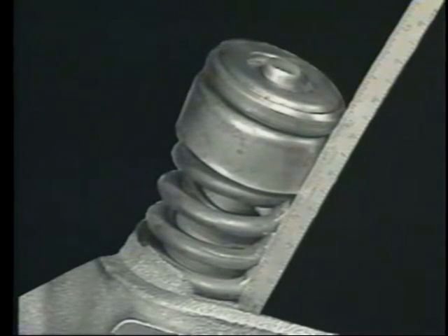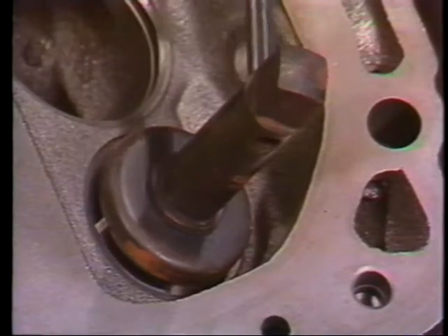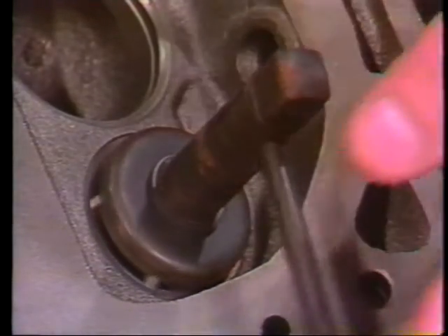The valve spring installed height is being measured in this illustration. When a valve face or its seat is cut, the valve will sit higher in the cylinder head. When the spring is installed in the cylinder head, it will not be compressed as much as it should. This could result in the valves floating at higher RPM.